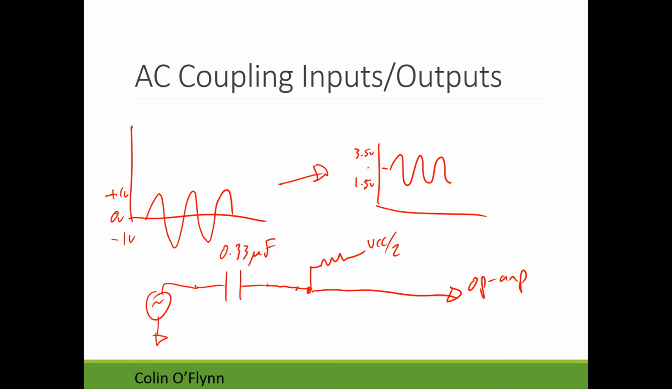You can simply do this with a resistor. So now the drive strength becomes limited. If this is a 1K resistor, this is your effective series resistance. But it's helping to pull that signal into your virtual ground.